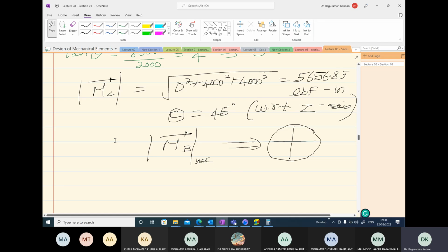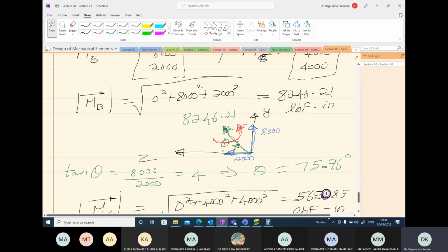We are going to use the resultant magnitude and calculate the stress. If you recall from your solid mechanics course, what is the formula for sigma from bending moment? It is M over I times the maximum value. Let's say the radius is c, I will write it as c. So this way we will find the stress for the circular cross section. It's very simple here. Why? Because if you take the resultant bending moment with respect to this particular axis, whatever this axis is, y and z.